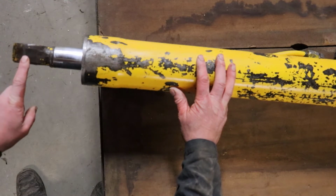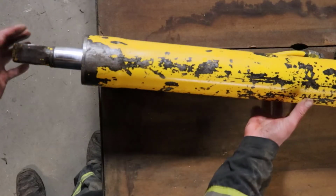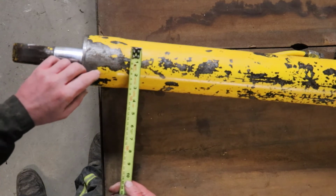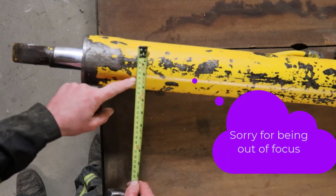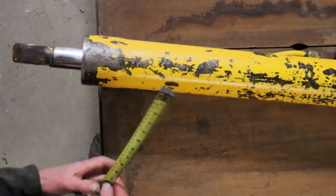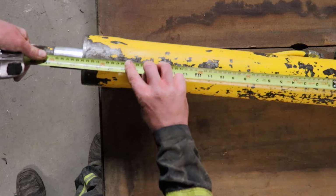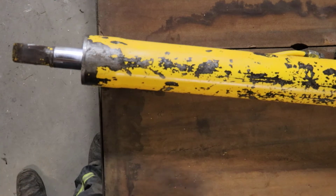This end here happened to be hooked to a blade of some sort, and this end was hooked to, what good fortune. So going off of the serial number, I was able to find the part number for this cylinder, and Caterpillar says it is a 65 millimeter bore, which I'll have to take it apart and see, but it might be a pretty heavy wall tubing. This is awfully heavy, and the stroke length was 450 millimeters. So right there should be 450 millimeters. So we'll see if this one's going to work.